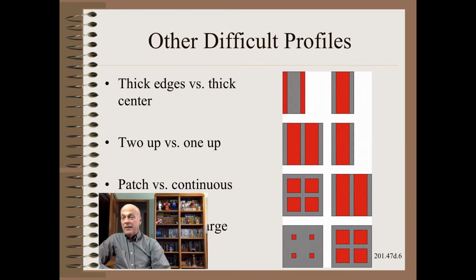There may be a big difference in the risk of thick or stiff edges versus centers. In general, stiff edges misbehave as a web by acting like two separate webs and wrinkling in the middle when they move inward just the tiniest bit. In general, thick centers wind a bit better, but better is only a relative term. They will never wind well.